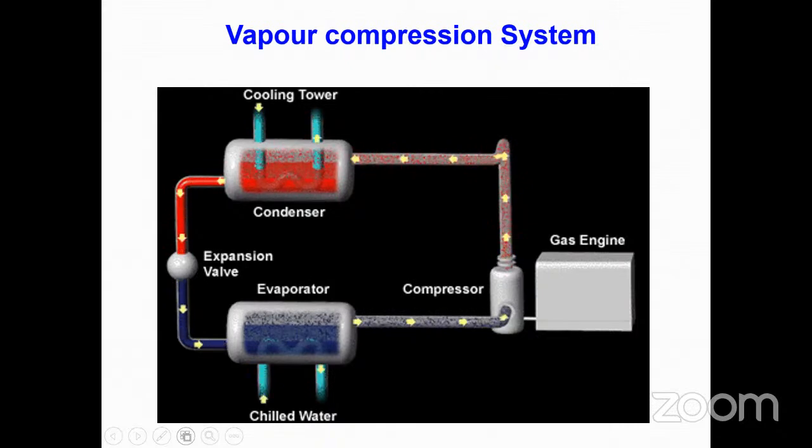In this water cooled system, we require a cooling tower, a condenser water pump, and also chilled water pumps, a secondary pump and a primary pump. For a larger building, we require a primary pump as well as a secondary pump for pumping the water to the AHU units through pipelines.